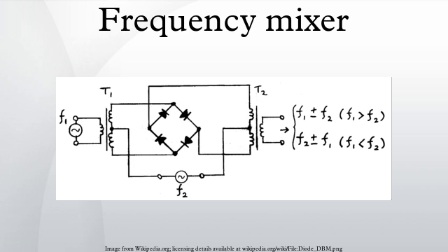The exponential can be expanded as a series, and can be approximated for small x by the first few terms of that series. Suppose that the sum of the two input signals is applied to a diode, and that an output voltage is generated that is proportional to the current through the diode. Then, disregarding the constants in the diode equation, the output voltage will have the form shown. The first term on the right is the original two signals, as expected, followed by the square of the sum, which can be rewritten as shown, where the multiplied signal is obvious. The ellipsis represents all the higher powers of the sum, which we assume to be negligible for small signals.